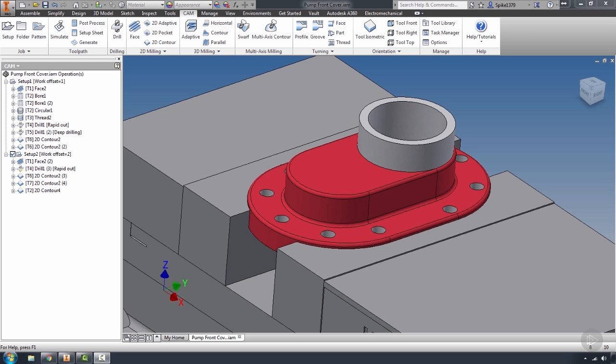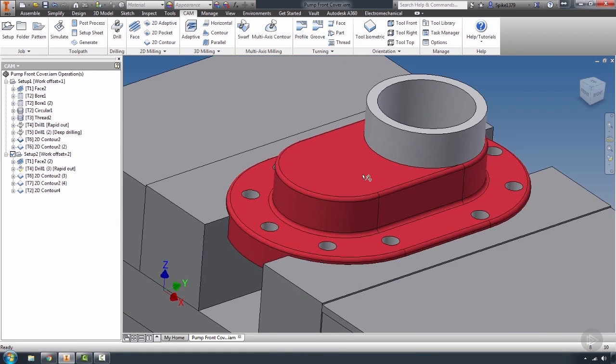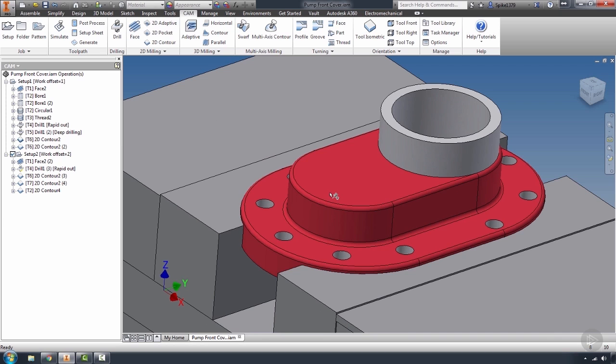A natural occurrence in manufacturing for all machine shops is the inevitable rev change within parts from customers or internally within your organization. Now, with most legacy CAD/CAM software, you would have to import the new part, place the new part, and then go through each toolpath and reassign each toolpath to the new geometry. Sometimes you would end up having to Frankenstein together, for lack of a better term, toolpaths, and you may actually keep older toolpaths assigned to old geometry for speed.